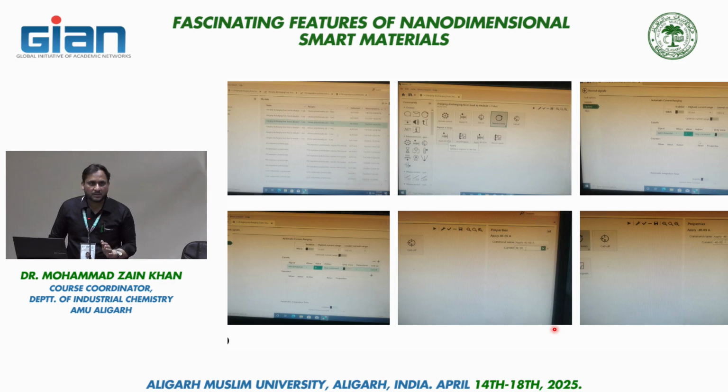We use the drop casting method, which is a simple method, but since we are doing it manually, you are developing the layer manually. That layer can be developed, but if I look exactly, the thickness will not be very uniform. So for laboratory studies, drop casting is a good method, but for large scale, for very reliable data, you have to use certain other methods in which some machine is involved. You will get a uniform coating. For example, you can use spray coating, the second method I explained yesterday.